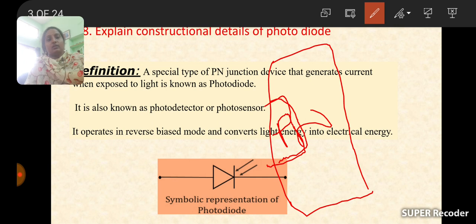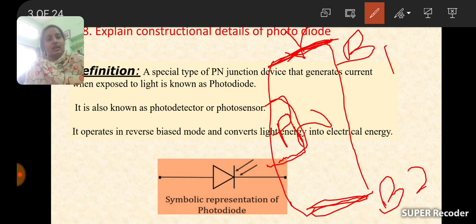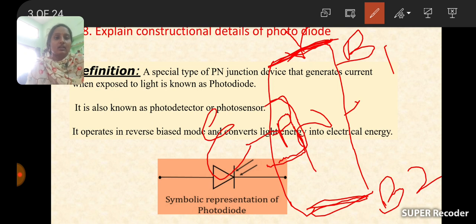The two sides of the n-type, bottom as well as top, are attached to ohmic contacts. These are termed as base 1 and base 2. So here P is considered as the emitter terminal, and the n-type semiconductor attached to the ohmic contacts gives base 1 and base 2.